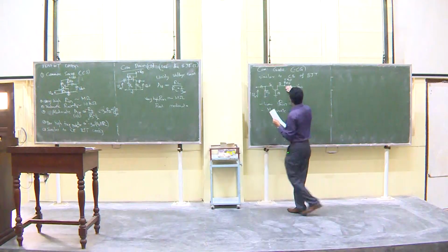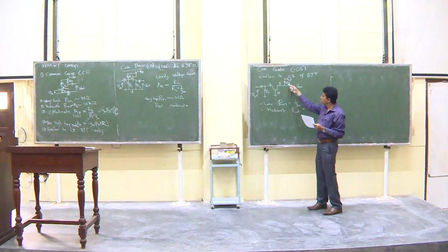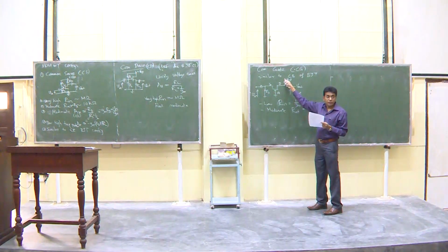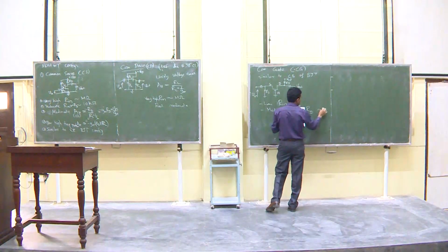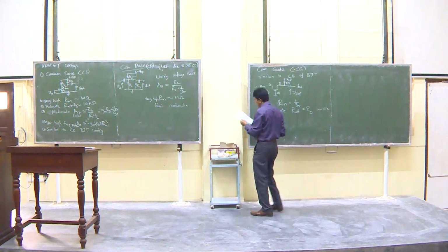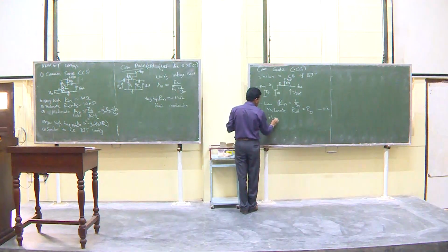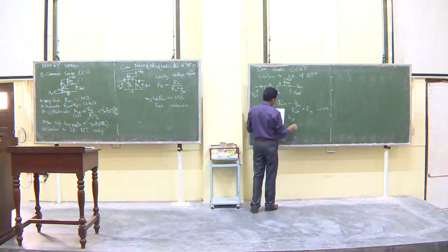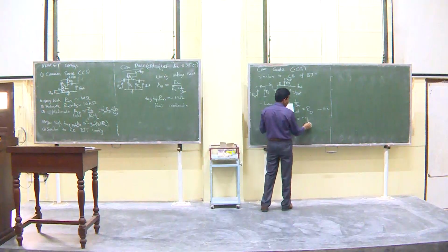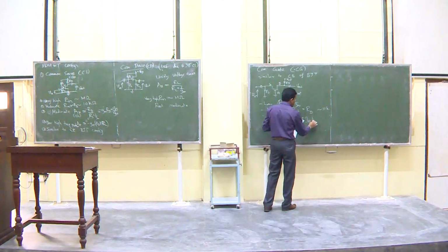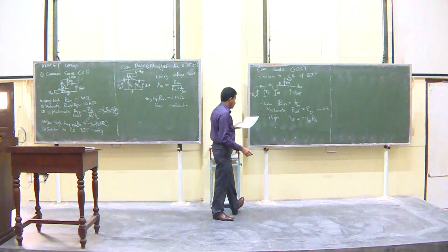Output impedance, when you look at it in the small signal model, this will be short circuited, so it will be basically this resistor there. So this is RD, in the range of maybe 10K or something. And high voltage gain, which is basically positive, this is a positive one, previous one is negative, GM times RD. You have a positive gain, GM times RD.